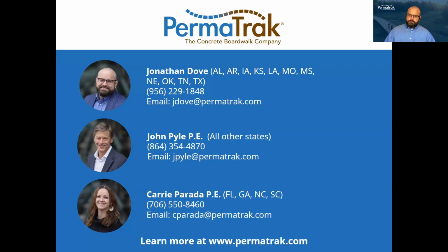The question about vinyl coated piles is a good option to protect and improve the lifespan of the timber pile. And I've seen that done, and you see that around boat docks, right? You see that all the time where you have the water rising and falling and exposing that timber. And that's where the timber gets in trouble, from a longevity standpoint. So protecting it with vinyl, absolutely, I would think that would be a good option. Yes.